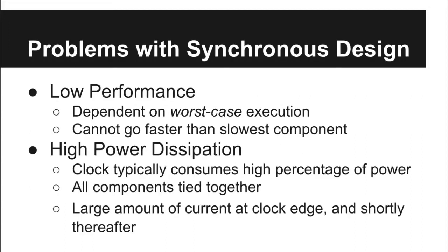First, some problems with synchronous design. Synchronous circuits generally have been favored in CPU design for the fact that they are easier to design, easier to test and debug. Their operation is more widely understood in the industry than asynchronous circuits, and the timing of the clock period makes it easier to regulate data flow, easier to control and predict when data gets transmitted between components. However, the synchronous approach is not without its share of drawbacks.